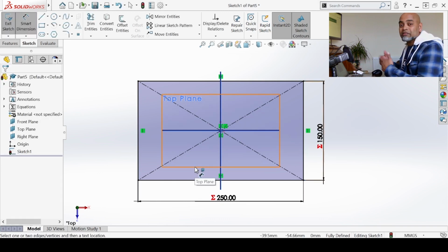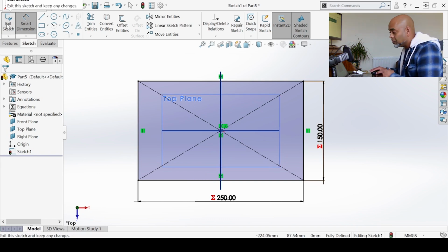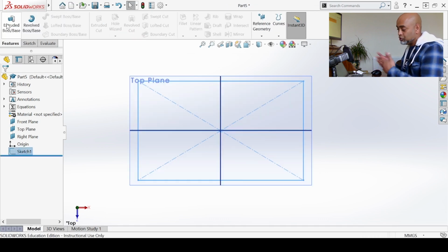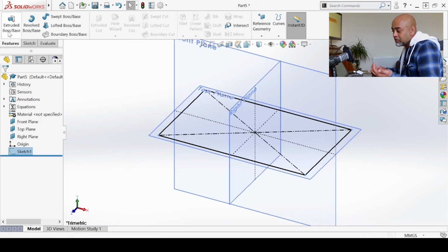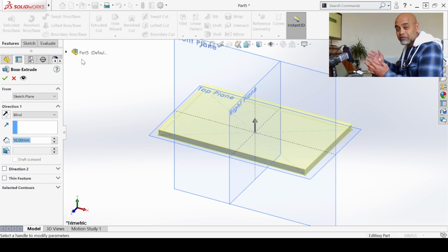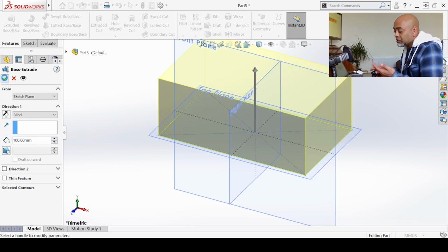They are then matched up against a variable, which is length and width. You kind of know where I'm going with this. I can use those variables to probably dictate the height of this. So what if I wanted to specify the height actually depends on the length every single time? I can create a dependent geometry. I can say what if the height is 80 per, this is a standard approach. You can go and say, well, that's that, green tick to confirm.